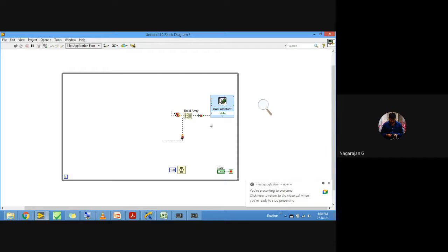Do you know that when a red LED is on, the yellow and green should be off. When yellow is on, red and green should be off. When green is on, red and yellow should be off. So we need to develop logic in such a way. We are going to develop a small traffic light application with not much requirement. Simple, like every 500 millisecond, one LED will be on.